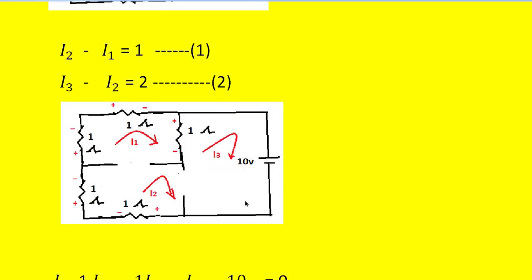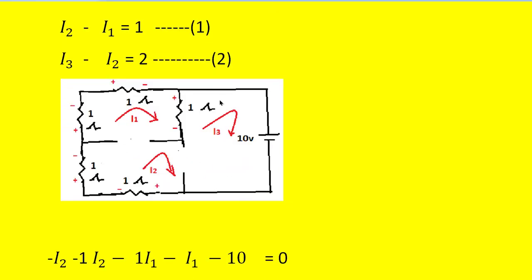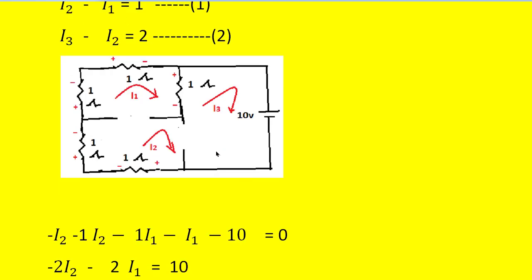Whereas the other elements are connected to each other, forming a loop. For that loop we can write the loop equation, that is, we apply KVL to this loop. So look at this. You start at one point. Let us say we start in the second loop. This is the 1 ohm resistor, and we get plus first and then negative in the direction of I2.